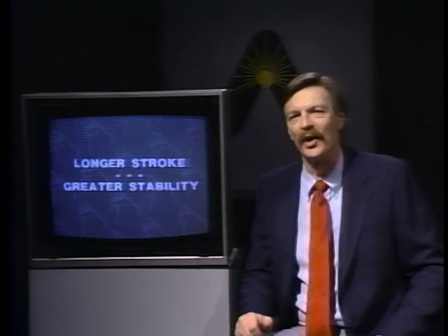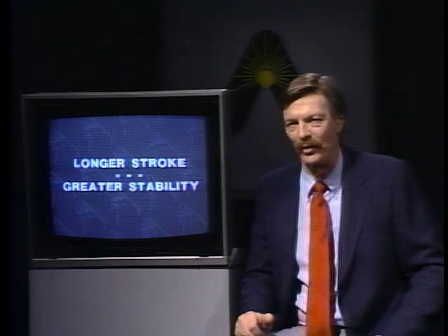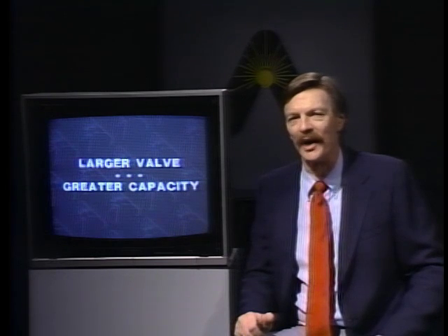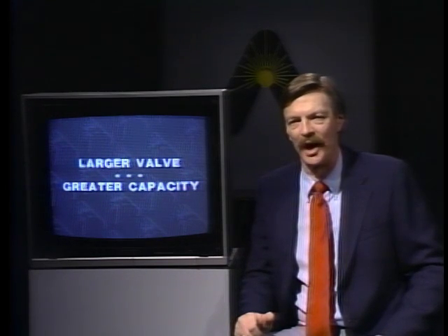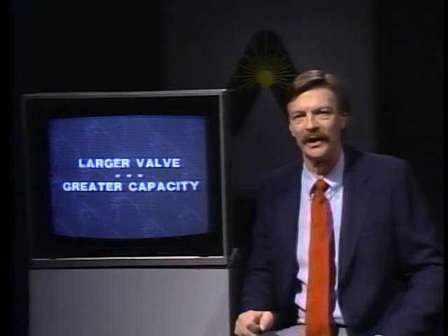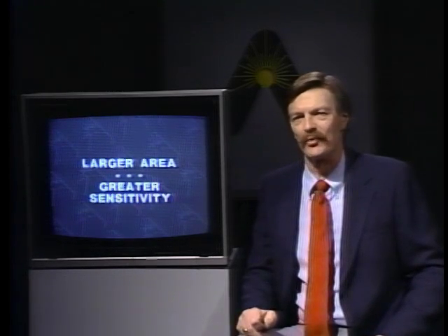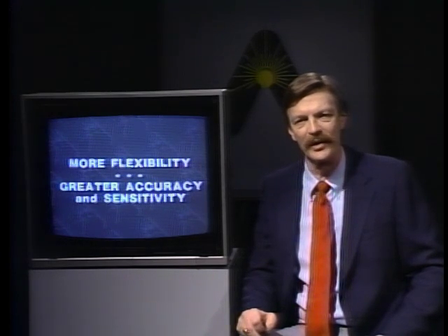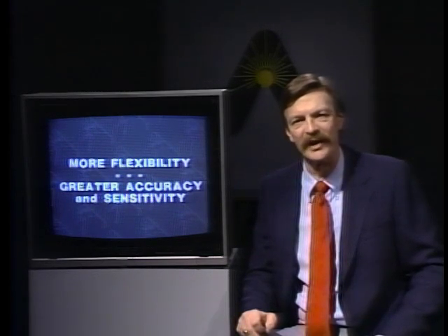The largest effect on the regulation curve may be seen by altering the controller. First, the longer the valve stroke allowable by the controller, the greater the stability of the PRV. Second, the larger the area of the controller, the larger the valve that can be opened, therefore the larger the capacity of the PRV. Third, the larger control area also responds better to small pressure changes. Fourth, the flexibility of the controller determines how quickly and to what degree valve movement is accomplished, affecting both accuracy and sensitivity.